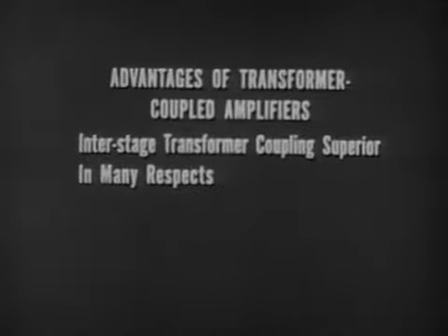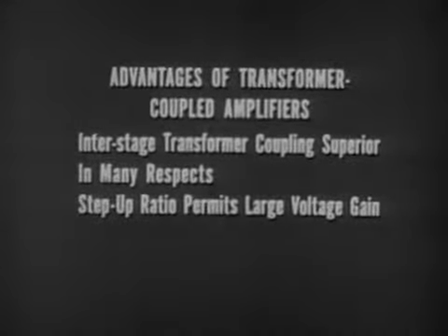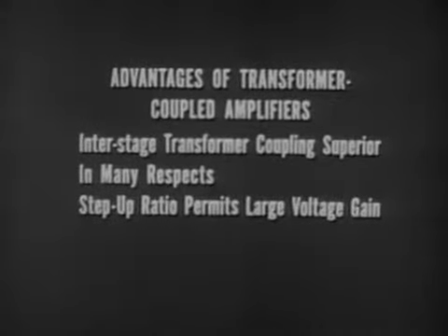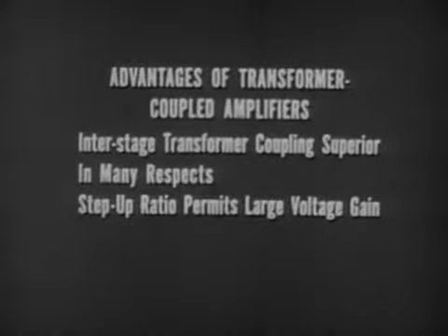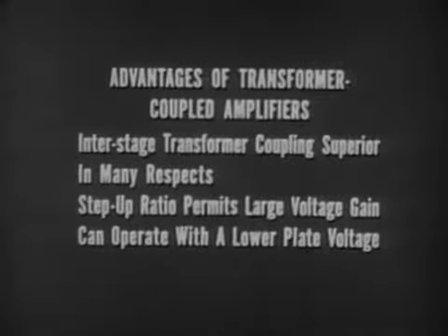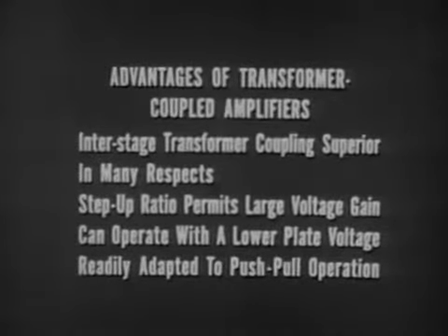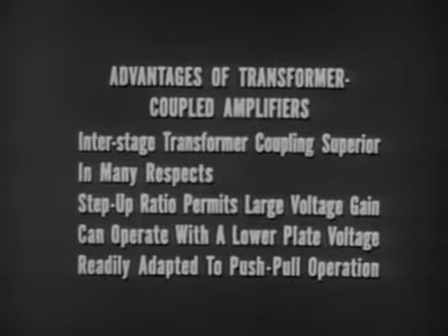Interstage transformer coupling is superior to other methods of interstage coupling in many respects. The step-up ratio permits the amplifier voltage gain to exceed the amplification factor of the tube. Transformer-coupled amplifiers can operate with a lower plate voltage. The circuit is readily adapted to push-pull operation.